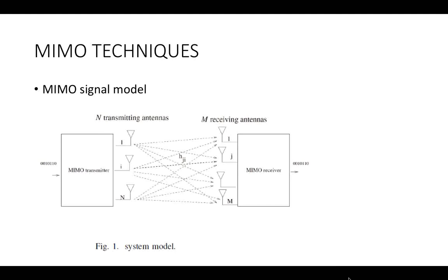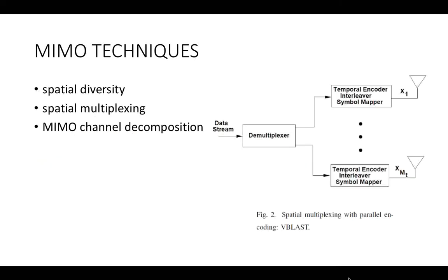So this is a MIMO signal, and now we will talk about the spatial diversity for the MIMO signal. The spatial diversity-oriented design will feature some level of repetition between the entries. For full diversity, each transmitted symbol must be assigned to each of the transmit antennas at least once in the course of the symbol duration.